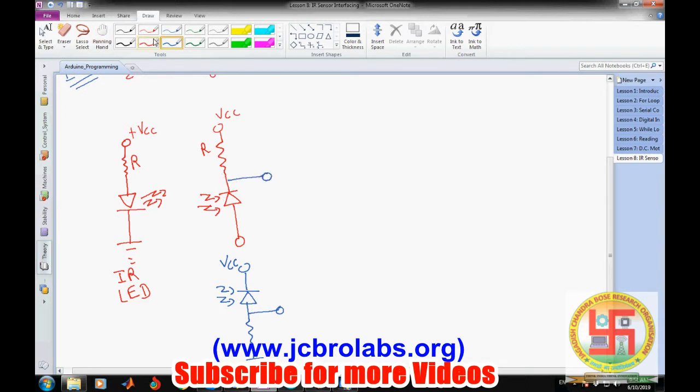Okay, so as we know, as soon as light is incident on this photodiode, it starts conducting. That means the resistance of this photodiode will be less. So let's take a case when there is dark, so it is not conducting. This output will be VCC. Now assume that light is falling on this photodiode, so it is conducting. That means the resistance of this photodiode is decreasing, so the voltage across it will also keep on decreasing. So we can say this Vout is a function of light intensity. Okay, so if we draw a rough curve, it goes like this.